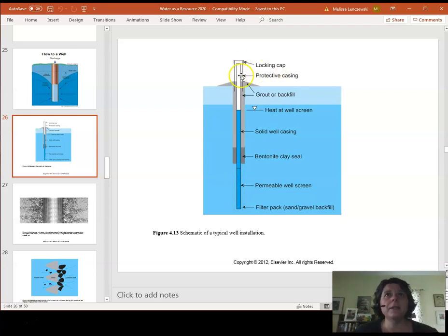So you have this piece of PVC pipe that goes down. What we do is we put right here between the borehole. So this is the borehole. We drill a bigger hole and then we put a smaller pipe inside of it. Well, that smaller pipe in that borehole, there's what we call the annulus, the area in between the pipe and the ground, and we fill that area in with concrete near the surface.